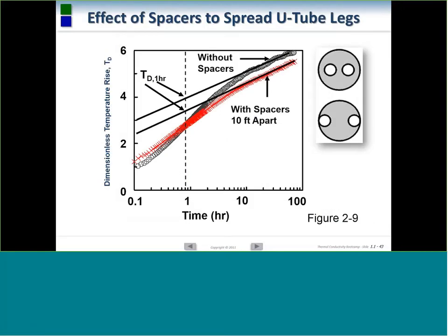Last slide. People ask about borehole spacing and borehole spacers, do they make a difference? Here's some more data from Oklahoma State University that shows what happens to the borehole thermal resistance values and what the conductivity tests look like with and without spacers. When you have pipe spacers on, you can actually see that the delta T and temperature stay lower over time than without spacers. Basically what they do is they decrease the borehole thermal resistance, allowing you to transmit more energy into the formation.